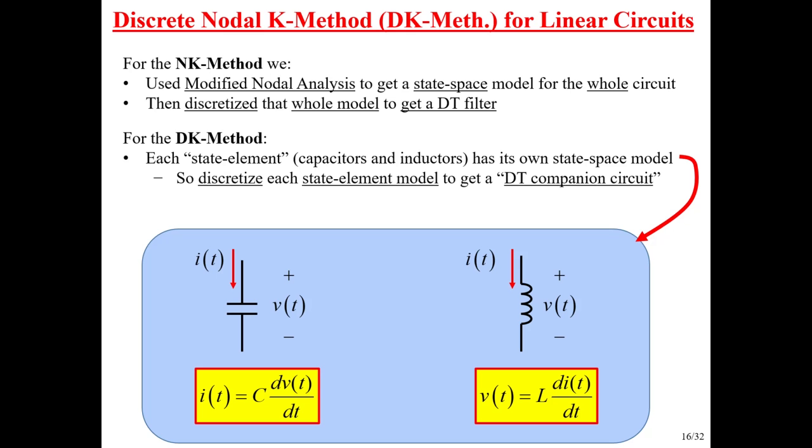But nonetheless, we know how to take a first order state space model. Well, all state space models are basically vector first orders. We know how to discretize a state space model. So take each of these state space models and discretize them themselves, and then interpret it. And what we'll see is we'll get a state element model. That's what we'll call this thing.